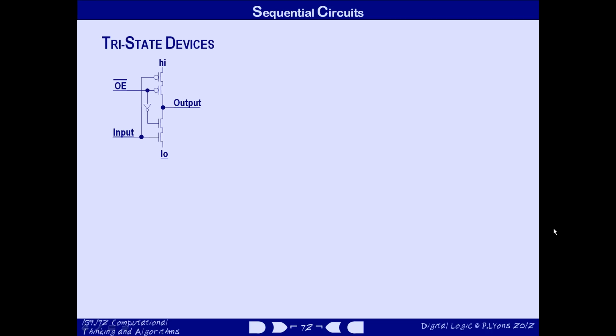And the output enable control signal gets fed through another inverter, an inverter inside the main inverter if you like, to a second isolating transistor. This one is active high, for reasons that we won't go into in this course, and when OE is high, this transistor also turns off, so that the output wire can't be connected to the low voltage power supply either.